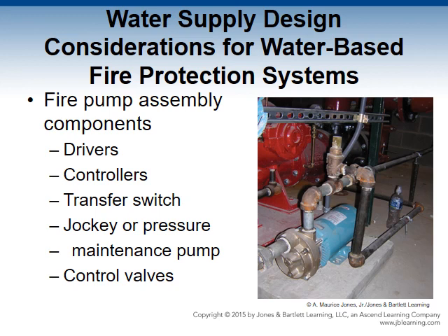The main relief valve is located on the discharge side of the pump and is required when the pump driver operates at a constant speed, when the suction and churn pressures are greater than the pressure rating of the component, or when there is an adjustable speed driver.